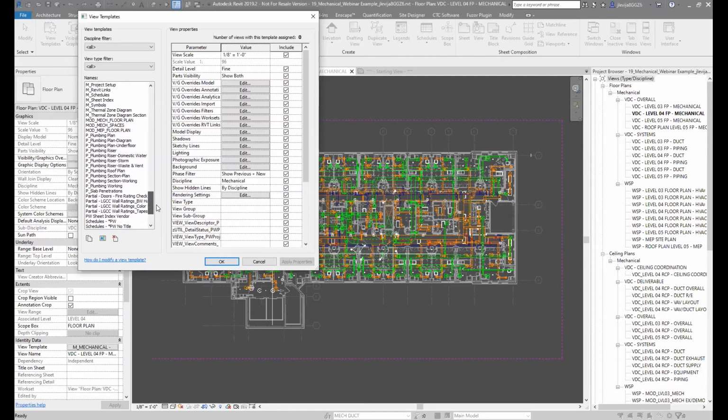I do have a couple other items out here, these _doc and such. That's from the engineer. So I wipe out some of the ones that don't need to be in there, and then I keep some of the ones that I may have to reference back. However, before you do any cleansing of a model, you should definitely put together a series of PDF files with all their sheets that you currently saw when you started the project.